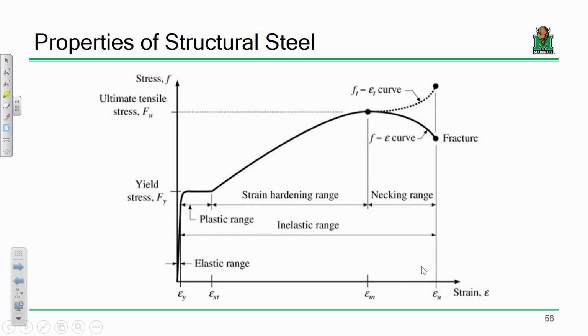So remember, the difference between inelastic and elastic deformation is elastic deformation is like the rubber band. You take a rubber band, you load it, you let it go, it goes back to its original shape. That's elastic. Inelastic deformation is sort of like what happens with a Coke can. If I have this can and I squeeze it a bit, it snaps back to its original shape. But if I take this can and I wail on it, it's a crushed can. It's stuck that way, right? That is inelastic deformation. Inelastic deformation is everything past the yield point.